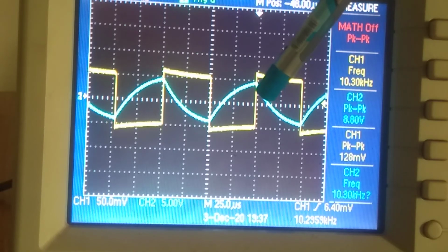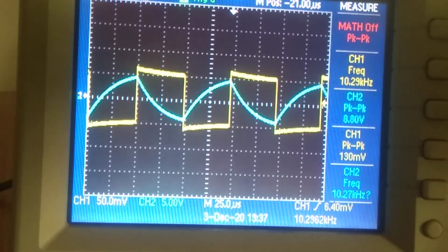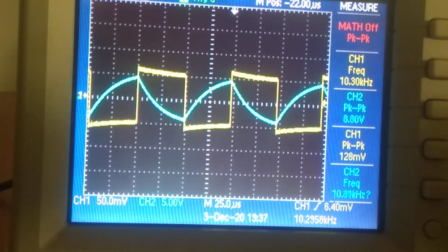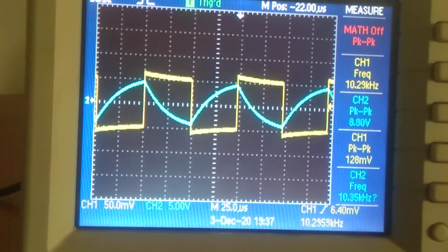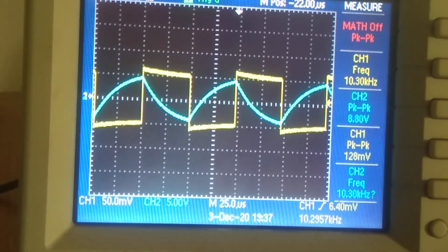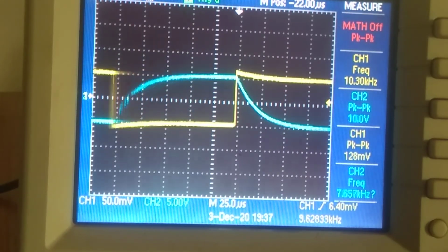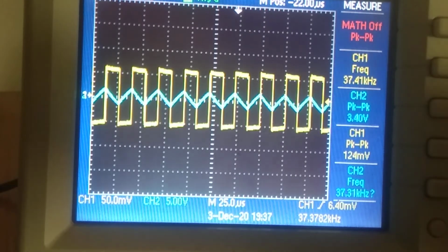This is happening because of that minus sign. Otherwise in positive it would be charging, and in negative it would be discharging. Now if I see the frequency at around 10 kilohertz, it is doing the same thing. Till now it is not integrating. Our point was 8.2 kilohertz. If I increase the frequency, let me increase it to 37, which means 5 times around that value.